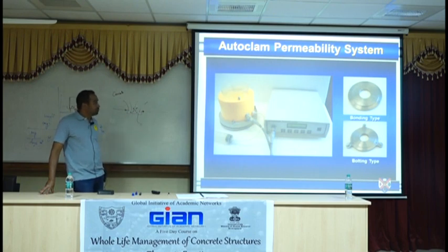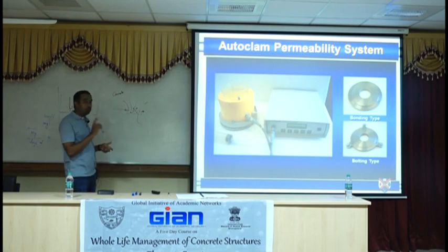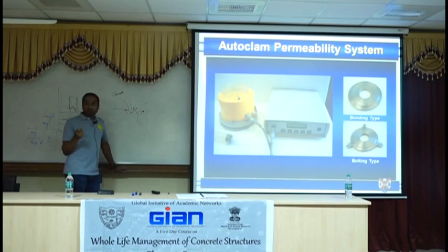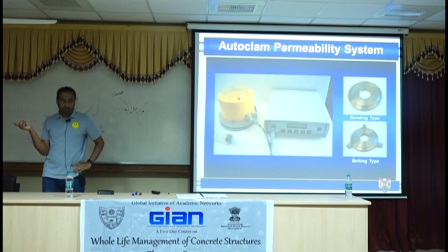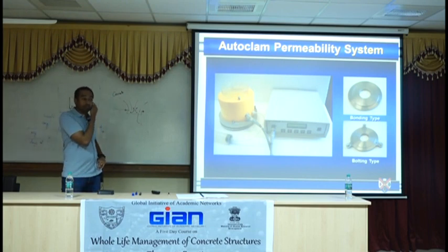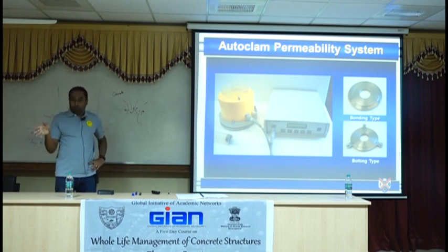So this test can do 3 tests, but not in one go. The sequence is very critical, okay? You cannot do wet concrete. You can only do absorption on a dry concrete. So don't do the water test first and then progress to absorption. Absorption has to be done before the water permeability test is carried out.